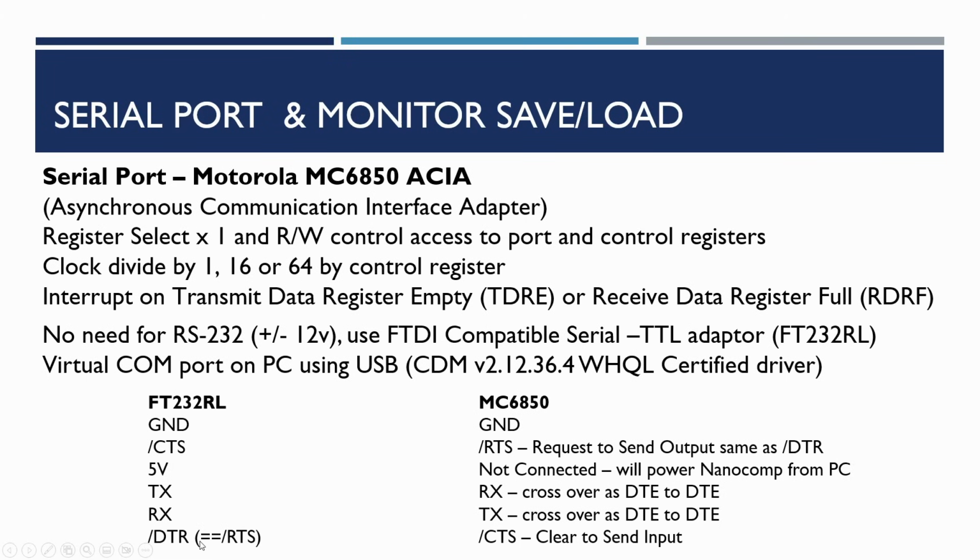The data terminal ready is the equivalent of request to send, and that's connected to the clear to send. So basically we've got the hardware handshaking signals connected to its opposite on the other side, and the receive and transmit are connected in a crossover connection. In days gone by, this would be known perhaps as a null modem configuration, whereby you're simulating the connections the DTE device would have connecting up to a modem.